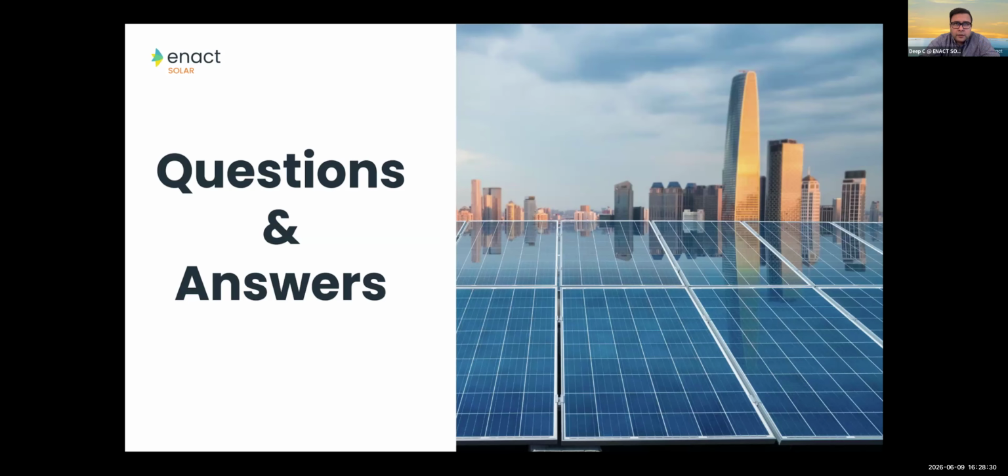Excellent. I would like to add that for customers who focus mainly on C&I, we have a PVCAD rooftop version, which shows the actual panel on the visual and has much more granular panel level properties showing on the drawings, because you then have to label them on the SLD and so on. But of course, when you get into the megawatt ground mount, the panels become objects. But you have both on PVCAD. You can decide whether you're doing rooftop or ground mount, and the abstraction helps you.